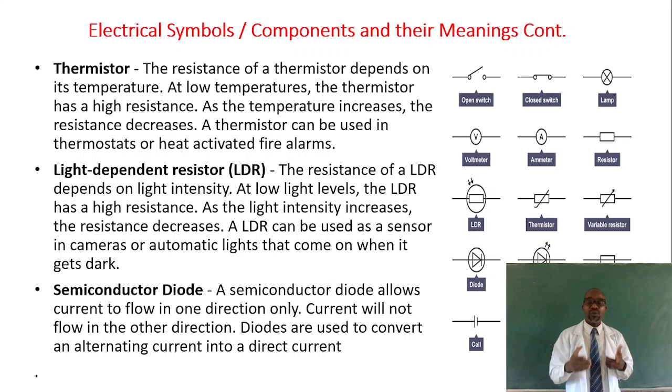That is why fuses are found in every electrical or electronic structure, because it acts as a protector. It's a device that protects. If current coming in is going to damage appliances around, the fuse comes into play by making a disconnection and stops current from flowing. That's what it does. All right.